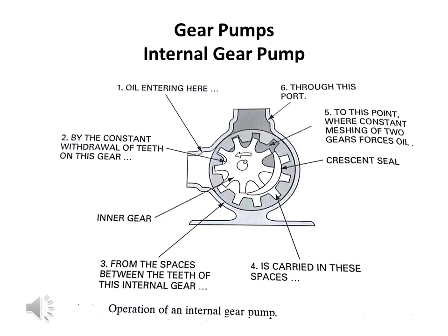Internal gear pump. In the internal gear pump, there are two gears, the inner gear and the outer gear, and look at the drawing, there is a crescent wheel fixed. It is fitted inside the pump, and the number of teeth of the inner gear will be lesser than the outer gear. The center of the inner gear is different from the center of the pump, so the inner gear is eccentrically located with respect to the pump.